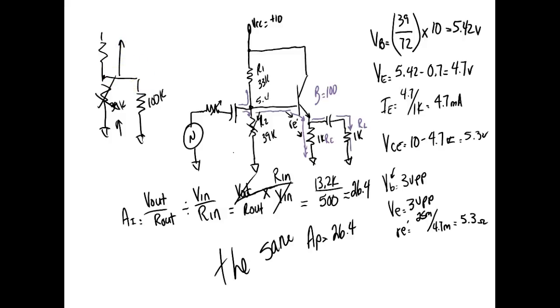Go up. If the base voltage goes up, what happens to the emitter current? It goes up. What happens to the transistor? It moves toward saturation. It's going to saturate. I mean, it's going to saturate hard, right? You understand that? So let's see if we anticipate that. So we should expect this voltage to go up, right? You understand?